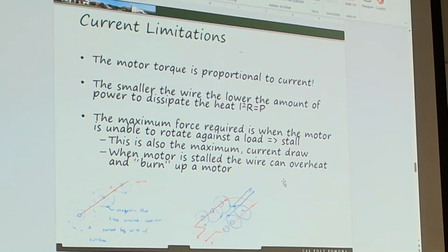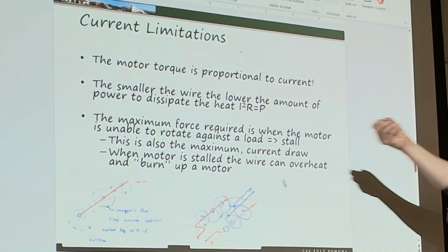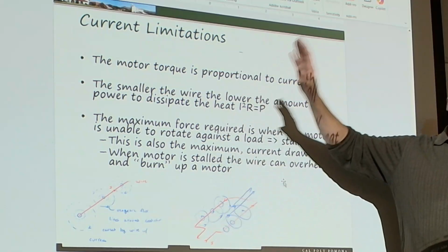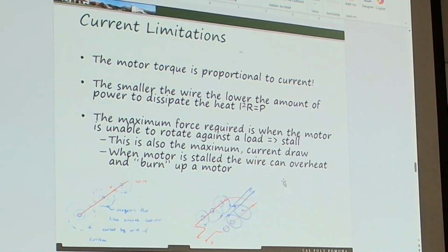So torque times omega equals power, equals IV, which becomes I squared R. Then that wire size has to support that current, right? If I have too much torque applied to that motor load, and I'm giving it maximum current, or more, then my motor will fail. Because my energy is now all thermal, and I can't dissipate that much because my wires are probably too small. So we need to size our motor.